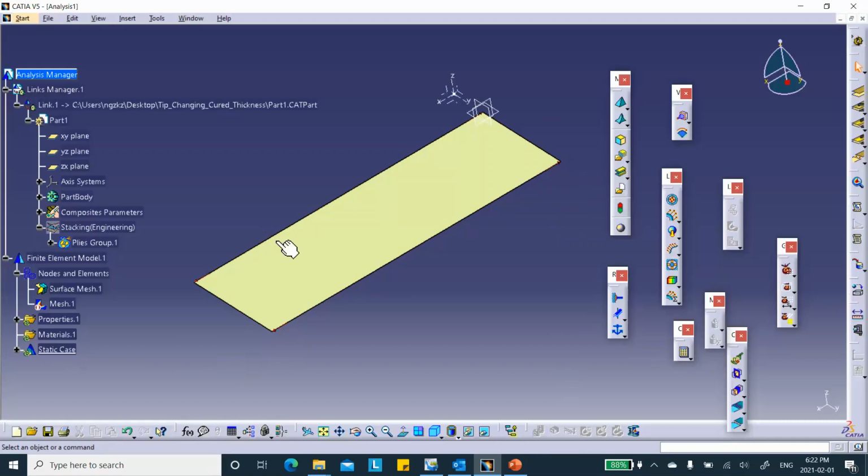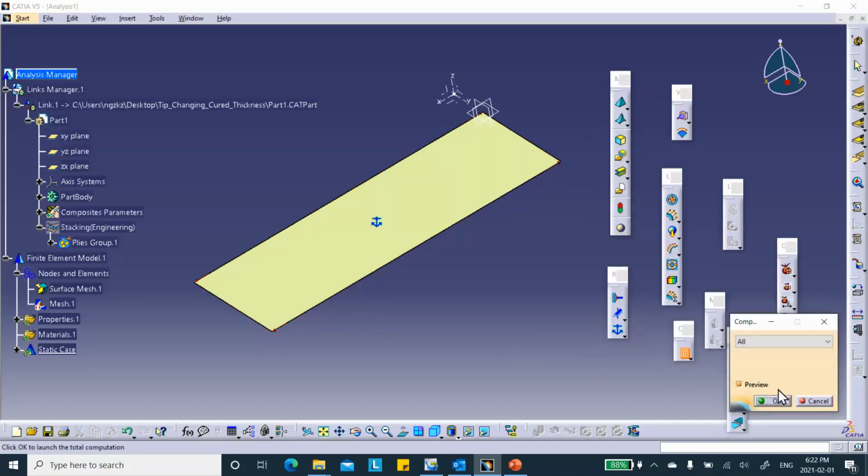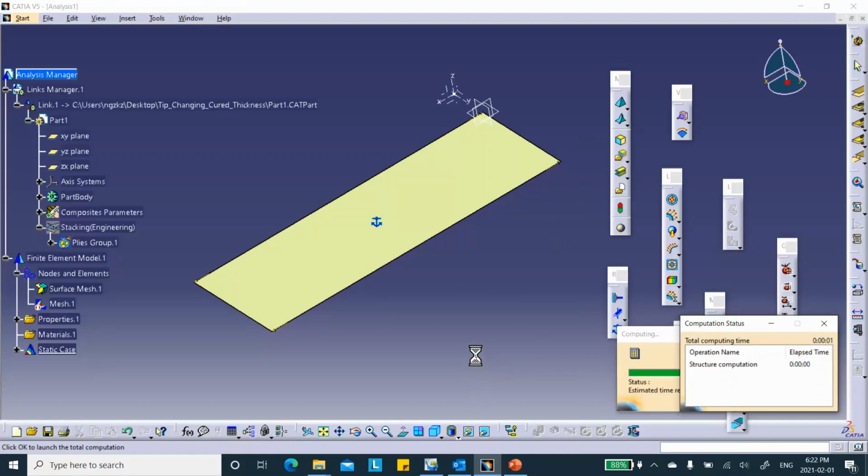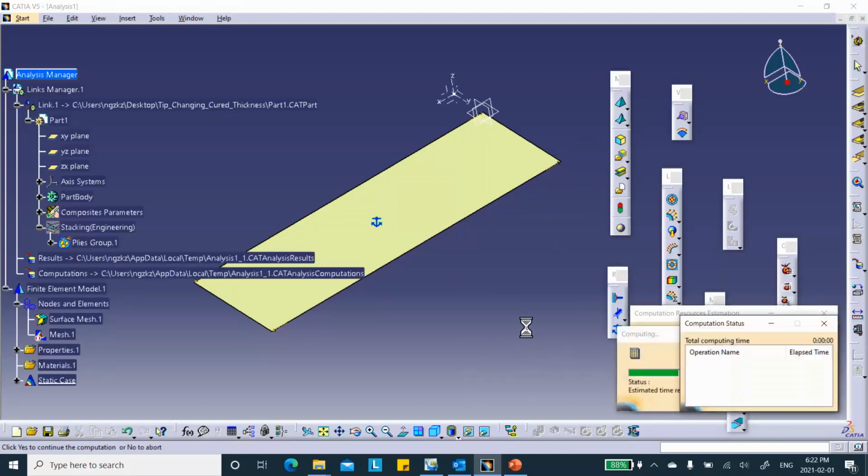You do that yourself. Or the easy way out, but be careful because this can get you into trouble sometimes. You think you have done it right, but you've got to be careful. That 1, 2, 3 rule can automatically be imposed as long as you know what you're doing with this anchor. If you look at the earlier videos on composites, the first 10 or 11, I did the 1, 2, 3 rule, I think, or at least in the first 3 or 4. You click on it, you don't have to select everything. Basically, it says that if you have a rigid body motion, take it away. All right, I can run this and there won't be any problem. It's going to run, and we're going to check out our results with hand calculations.